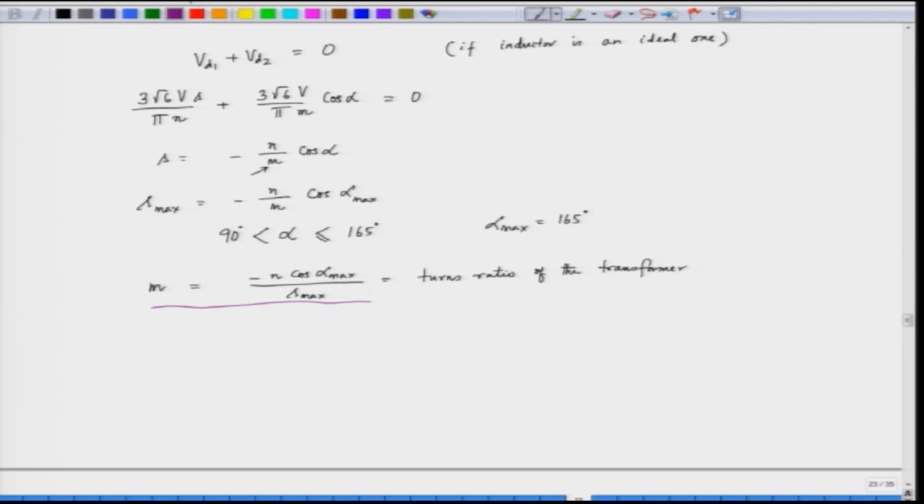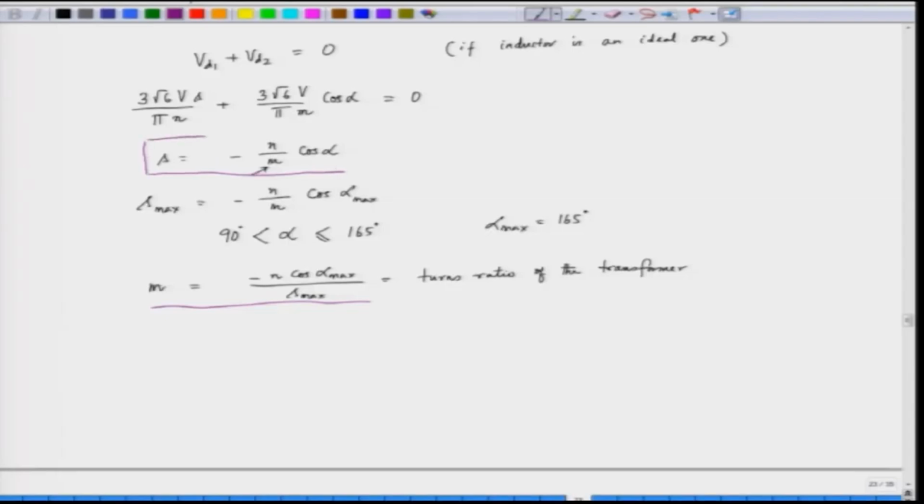So, we conclude here by observing that we can vary the speed of the induction motor by controlling alpha. This is our equation which shows that the slip of the induction motor can be controlled by controlling the triggering angle alpha of the converter. As we go on varying the triggering angle alpha, the slip can be controlled, and slip has to be between 0 and 1, and hence it operates in the sub synchronous speed, or speed below the synchronous speed. So, we stop here for today's lecture. We will continue with the slip power recovery scheme in the next lecture.